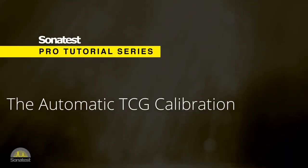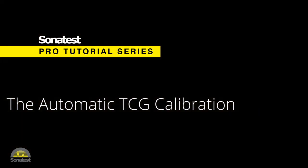Hello everybody, today's tutorial explains how to do an automatic TCG curve using the TCG, DAC and DGS wizard. The TCG or time corrected gain calibration should be the last calibration that you set, since the others could affect the signal response of your configuration.